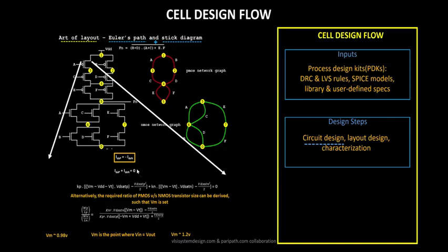In this case, the typical requirement is that the drain current of the PMOS and the drain current of the NMOS, if you add them, equal 0. That's the standard case. When you make them 0, you attain this particular equation, based on what value is needed. For example, if you need a certain value of the switching threshold, you keep that as a constant, and you can design everything based on keeping that switching threshold value as what you need.